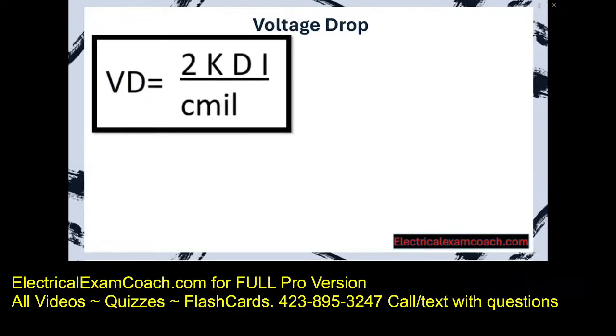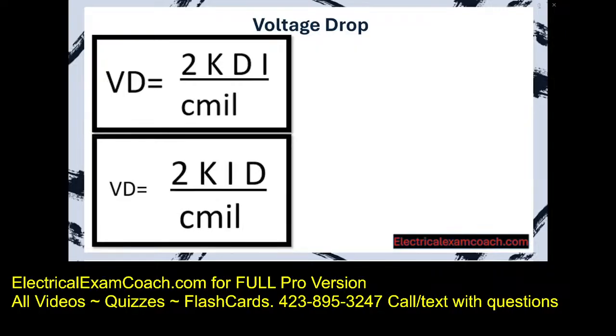Voltage drop equals 2 kDi over C mil. And that is an excellent formula, and it's actually the one that I use. But I've rearranged it so it's easier to remember. I do it like this: 2 kid over C mil. Easy to remember and easy to plug in.